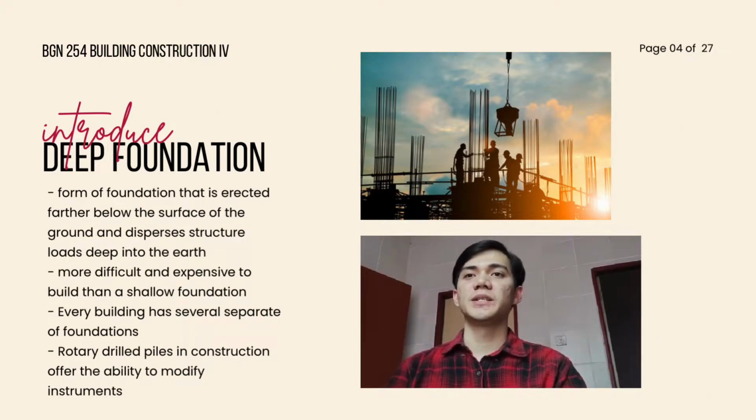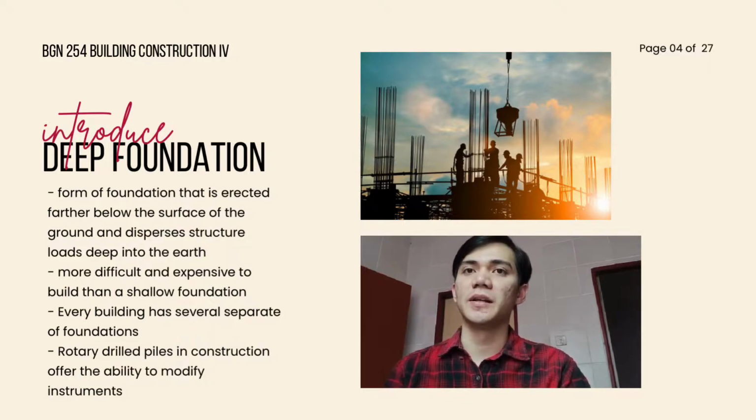A deep foundation is a form of foundation that is erected very far below the surface of the ground and transfers structural loads deep into the earth. Such a foundation often has a depth to breadth ratio larger than 4 to 5. It offers fewer site restrictions and the advantage of supporting more favorable soil conditions. A deep foundation is more difficult and expensive to build than a shallow foundation.